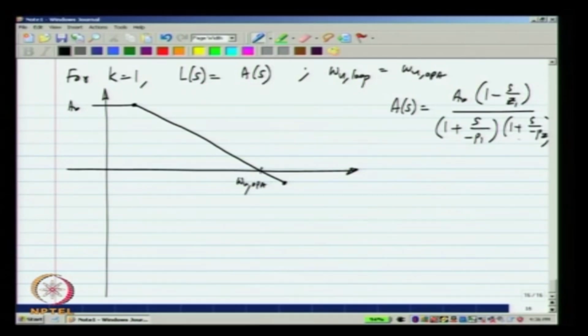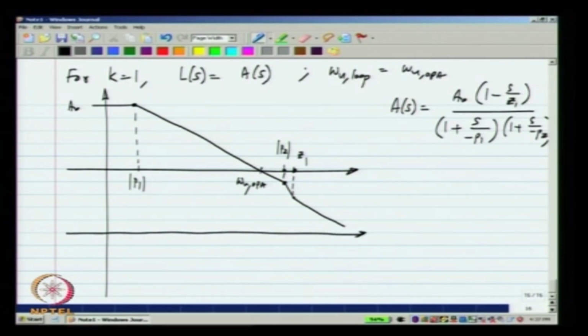This we have seen during our discussions of stability analysis, and also these zeros have to appear beyond the unity loop gain frequency. Okay. So, this is the condition that we must satisfy, and it should be beyond by a certain value. And how do we determine that value?